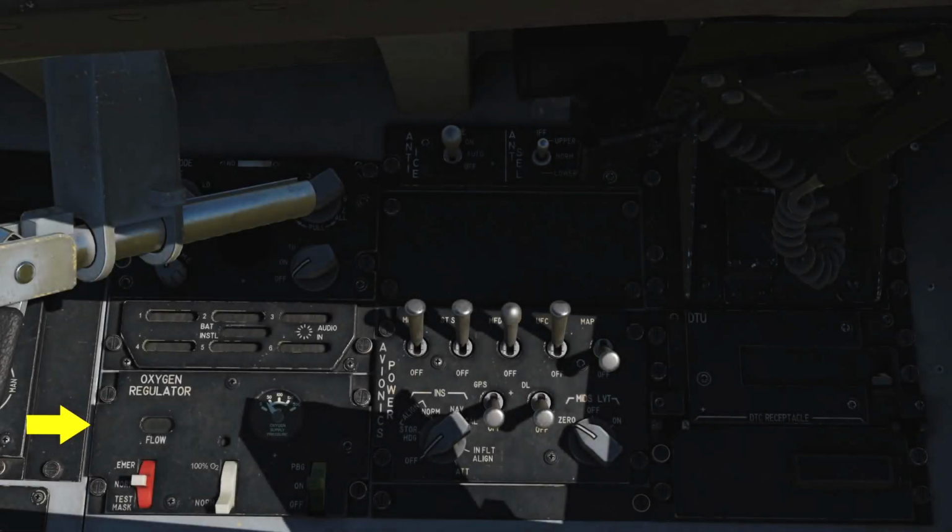kit. The oxygen regulation panel controls the flow of oxygen to the face mask. The supply lever enables the system to be off, supply air in the on setting, or it also includes pressure breathing for G with the PBG setting. The dilute lever can be set to normal O2 mixture or 100% O2. The emergency lever can set the system between emergency, normal, and a mask test. At the top of the panel is a gauge to indicate the PSI in the O2 system.